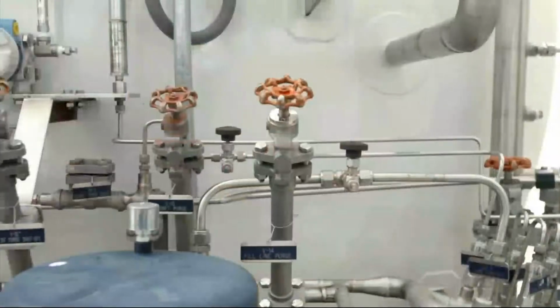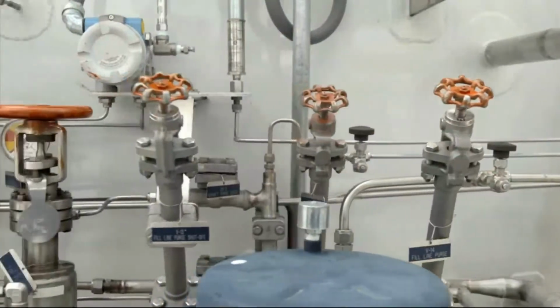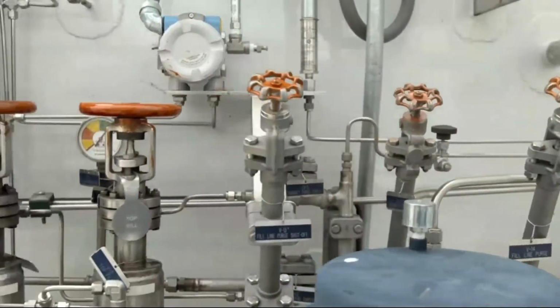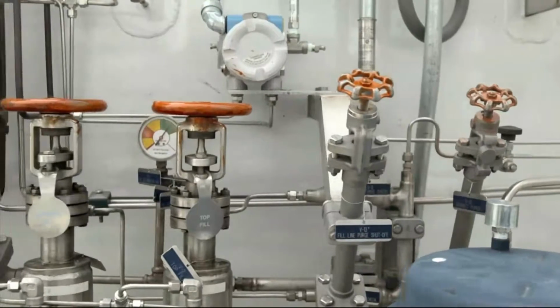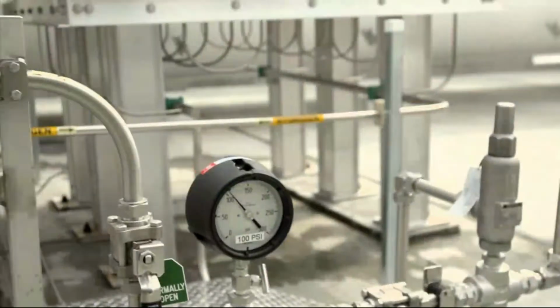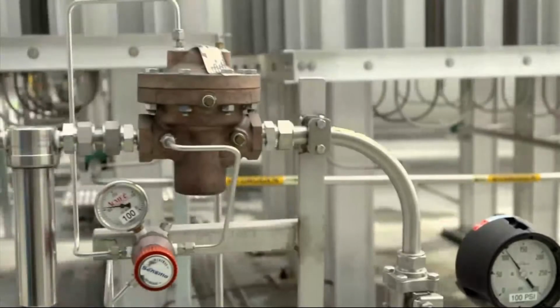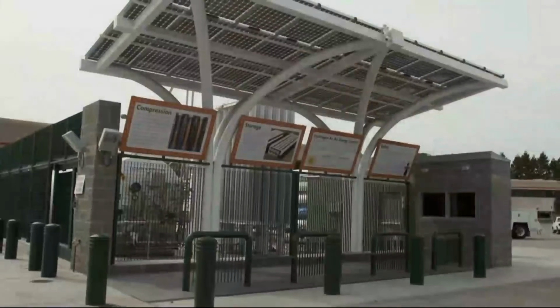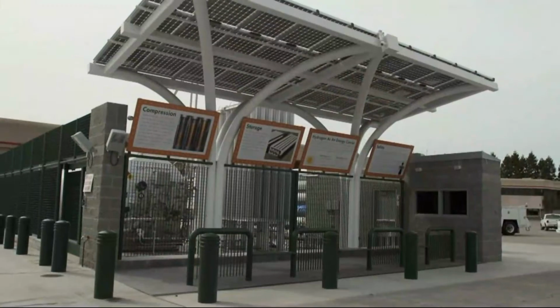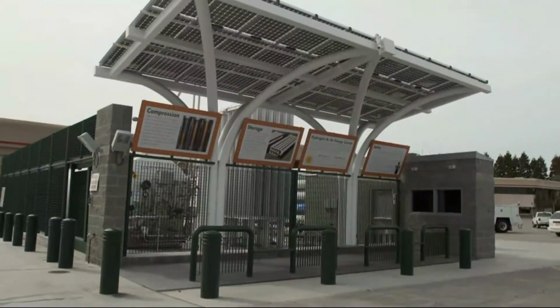To work safely with hydrogen, it's important to remember that it takes hardly any energy to ignite it. A spark of static electricity from combing your hair is about 1,000 times more than the amount of energy needed. The key to working safely with hydrogen is eliminating any possible sources of ignition.